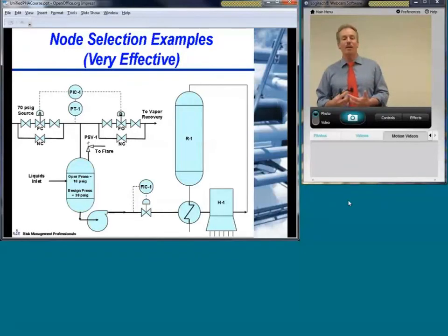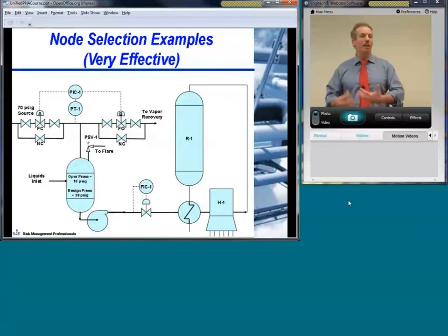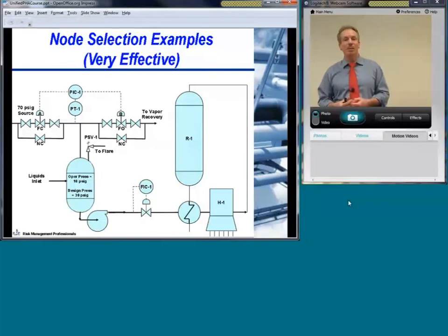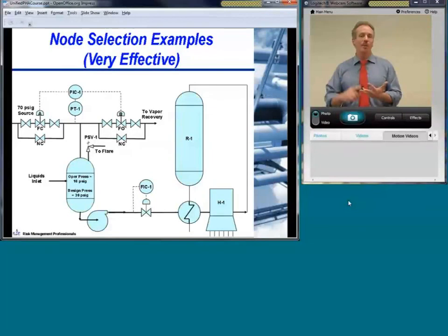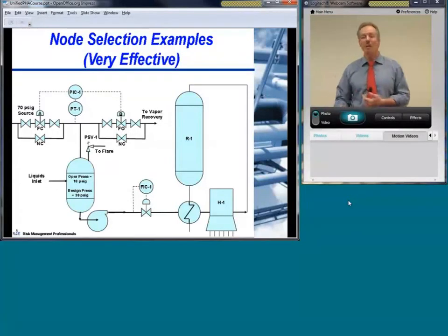So in a situation like that, you can go through that entire area for the HAZOP study very simply. You're talking about the same kind of consequence phenomenology at the same time, and it's very clean and easy to find things later. So think about process dynamics, what's happening with the system as you're defining the nodes. Now you also notice that beneath the heater, it is a fired heater, there are some red lines. Typically what we find is for a fired heater, the fire control system, any sort of flow of the combustion air, all those things are good to address as part of a separate node.